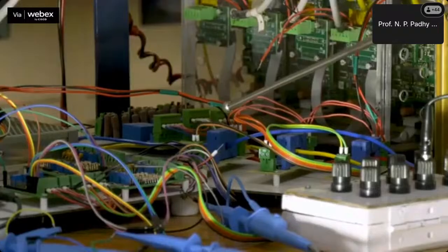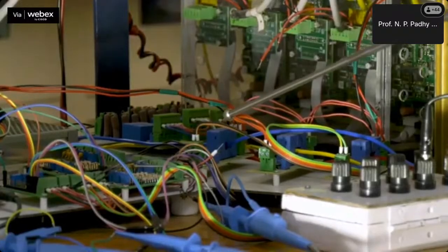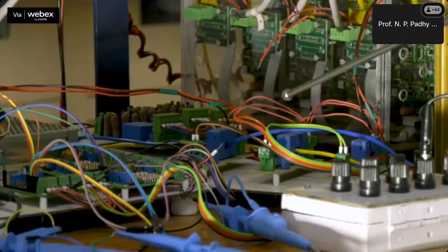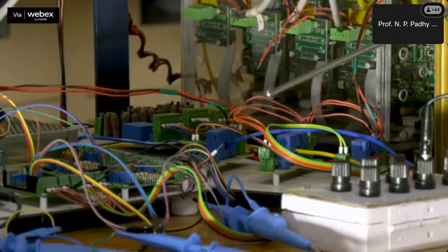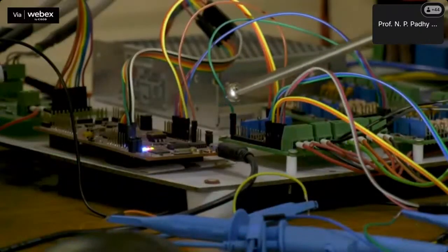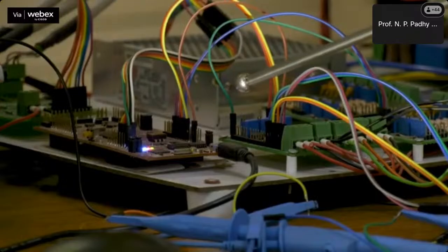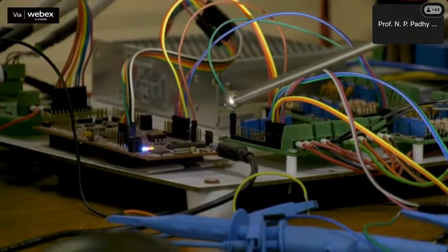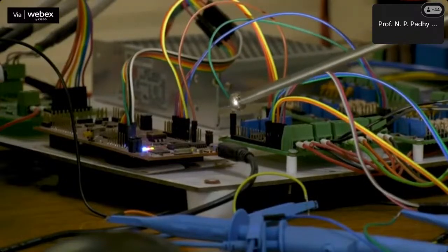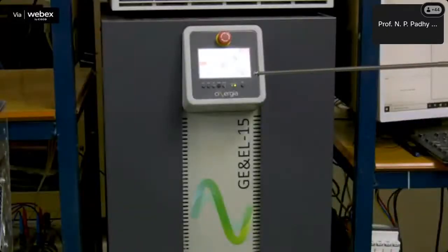Voltage and current sensors are used to measure the voltage and currents of the AC bus and DC bus in the DC microgrid. The measurements are given to the DSP controller for processing and PWM pulse generation to control the converters. Let us discuss the hardware setup component-wise. First, we can concentrate on the grid emulator.